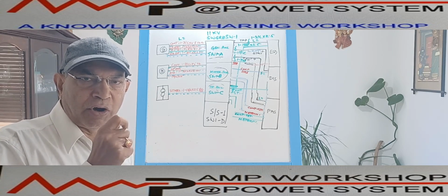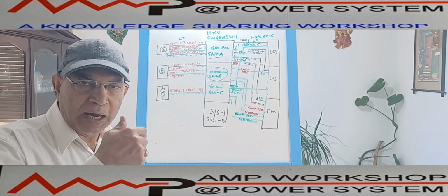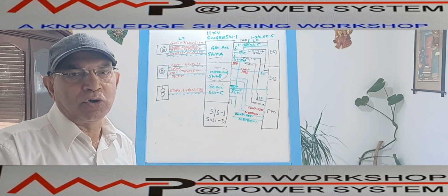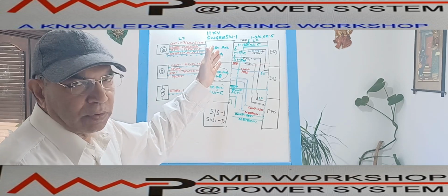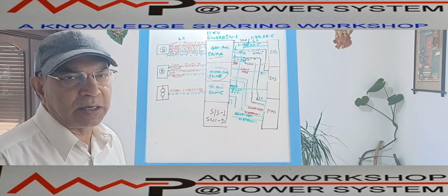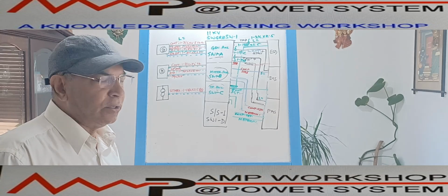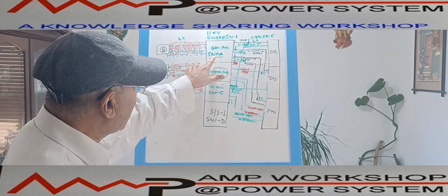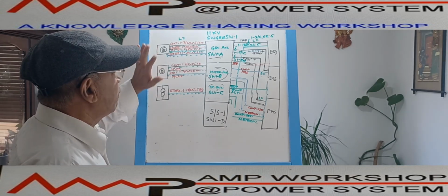The valve is a solenoid. In that solenoid, a signal is going for the opening, closing, or the opening portion control. So that signal is also going from the AVR and governor. If that AVR and governor are a part of the generator switchgear panel, then that cable also has to be connected. So if we look into this, the generator switchgear panel is connected with the generator skid with 4 different cables.